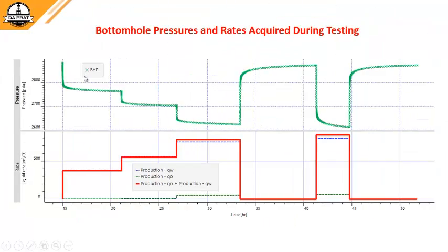These are the bottom hole pressures, which, to tell you, were acquired with an electrical submersible pump, because offshore you are limited, and in many cases when you realize that the well is not flowing naturally, you need to assist with a pump just for the test, I mean.